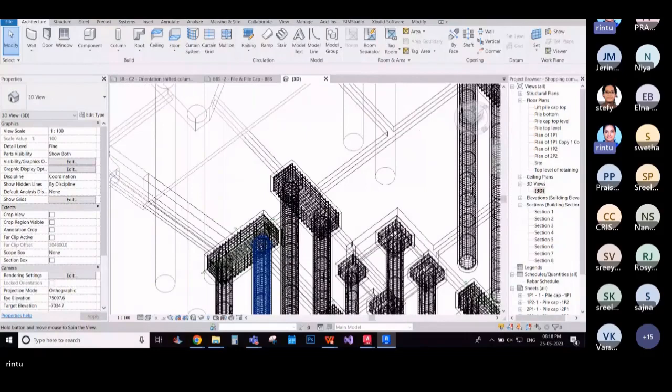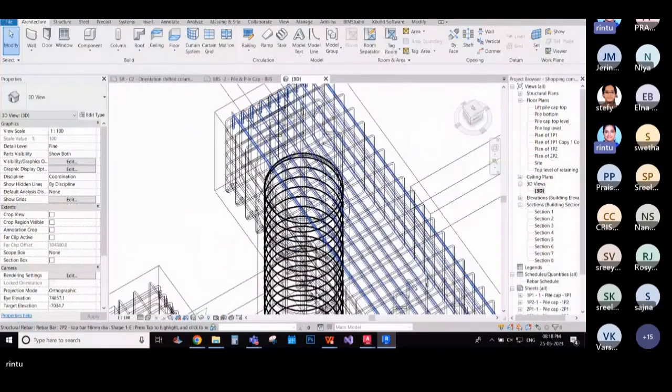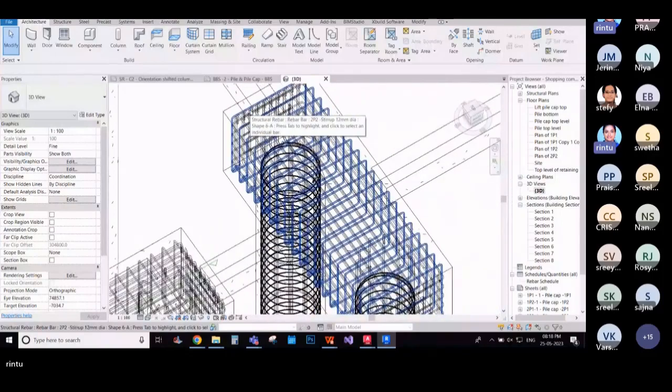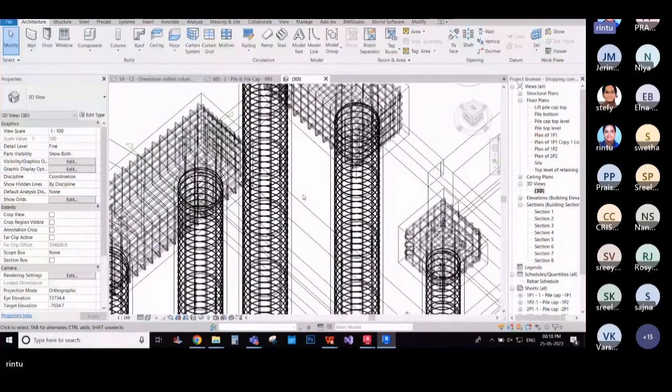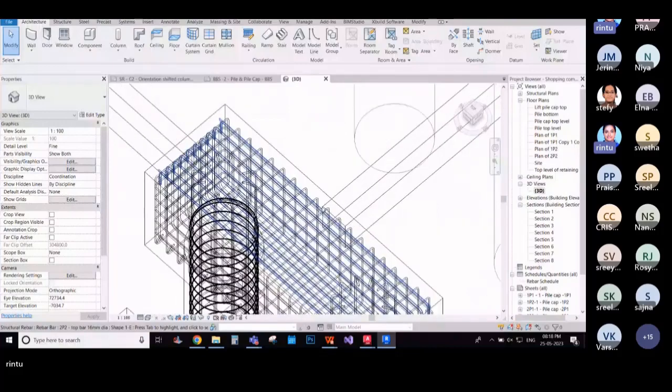Now this is a stirrup, the vertical reinforcement provided in the shorter direction. This is the longer direction, upper top bar. It's a U-shaped bar, as you can see. Don't worry, this is a wireframe, that's why it's overlapping here and there. Now it's a top bar. Now I'll just highlight the bottom bar, the bottom U-shaped bars. Then we have the side face bars.